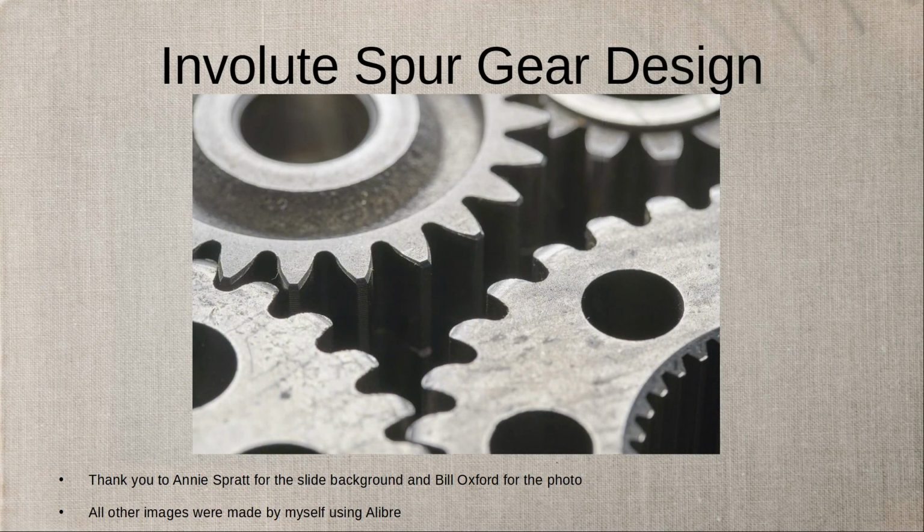In this video, let's go through a different method of involute spur gear design. If you're just tuning in, please see the last video that was put up, where we go through using an equation-driven curve to model this, as we're not going to go through everything that was covered in the last video. This video covers more of an approximated method of creating the involute profile of a gear tooth, and the approximation is really useful for those who cannot have the capability of generating an equation-driven curve in their CAD platform, or at least not one in a way that would be useful to model this kind of gear.